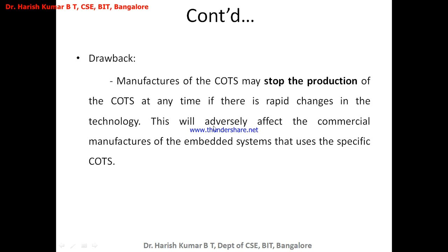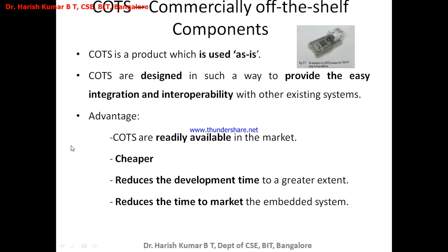At the same time, there are disadvantages or drawbacks of using COTS as well. If the manufacturer of the COTS stops the production because of rapid changes in technology, this will adversely affect the commercial manufacture of the embedded system that uses these specific COTS. Say, for example, I was using in my embedded system this product which provides me the TCP/IP connection.